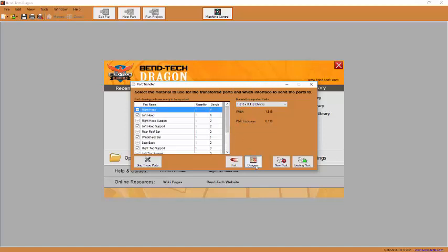If you send them all to a designer, they will open all in separate windows, and you can change things like the part name that's going to be drawn on that part, for instance, or the kerf width of your plasma stream if you'd like it tighter, or if you'd like to adjust the lead in and lead out information.